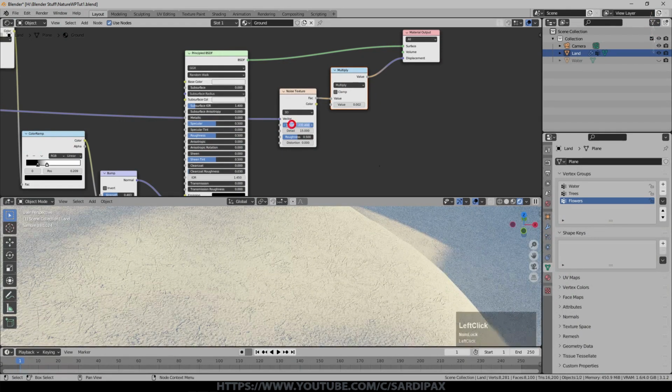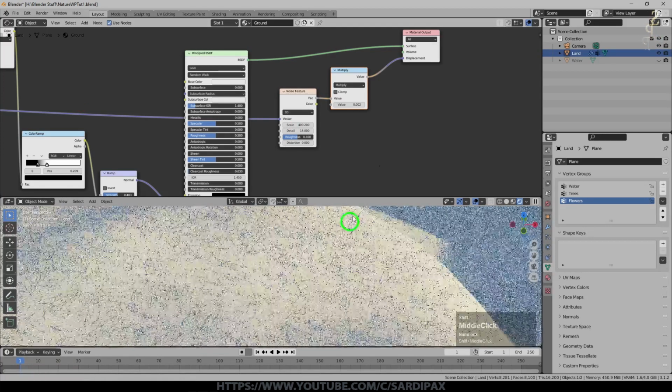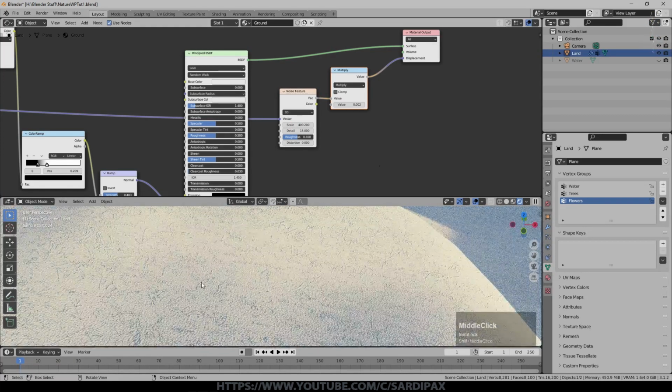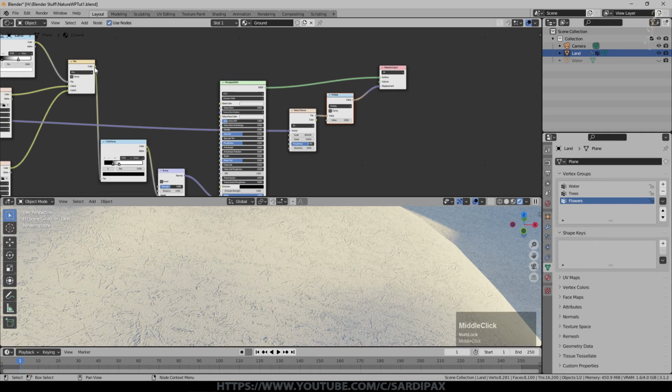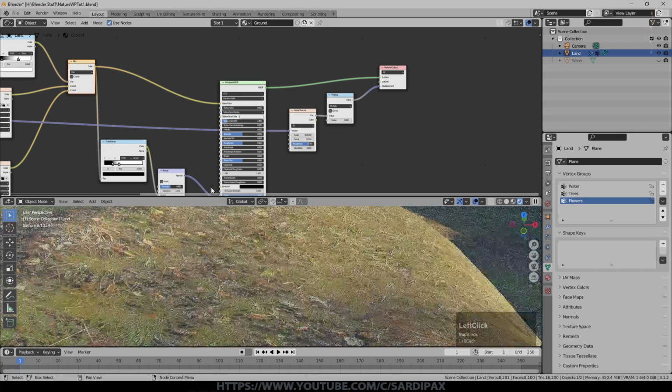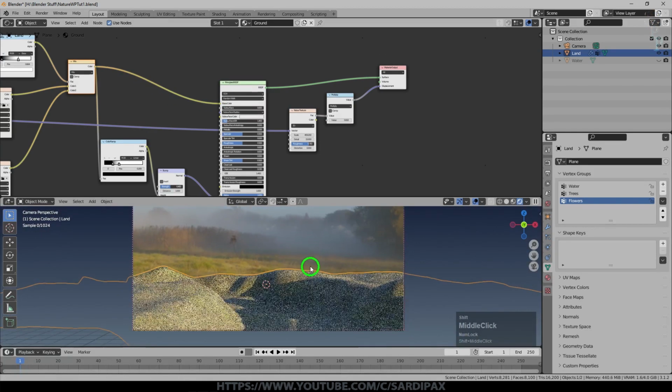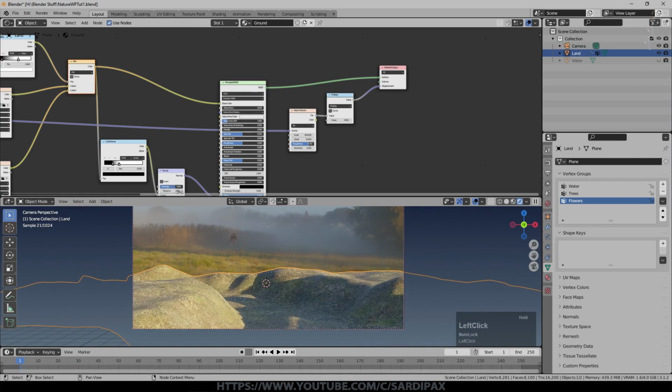There we go. So that's getting better, and I'll turn the noise scale up even higher, and it just adds a little bit more noise to the scene and more variation. And with nature scenes, the more variation in things, in textures and colors, the more natural it looks. So now we can plug our original color back into the landscape, and we're getting a little bit more there, and we can perhaps increase the strength of that a little bit as well.